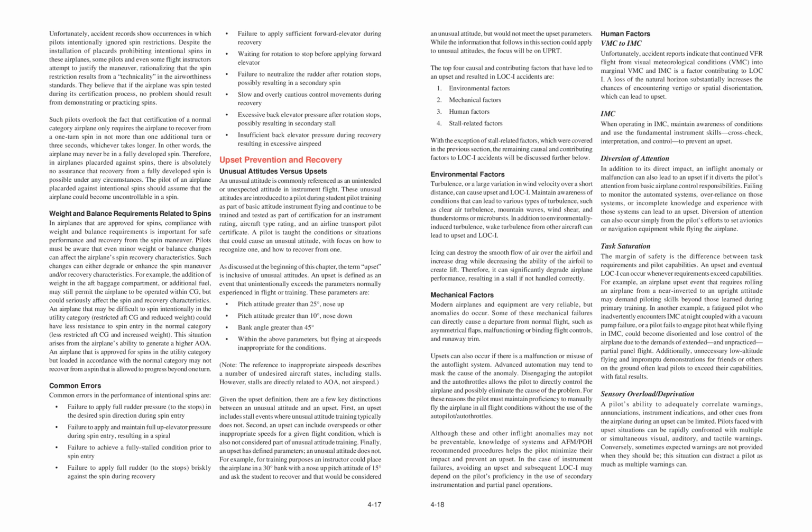IMC. When operating in IMC, maintain awareness of conditions and use the fundamental instrument skills, cross-check, interpretation, and control, to prevent an upset. Diversion of attention. In addition to its direct impact, an in-flight anomaly or malfunction can also lead to an upset if it diverts the pilot's attention from basic airplane control responsibilities.